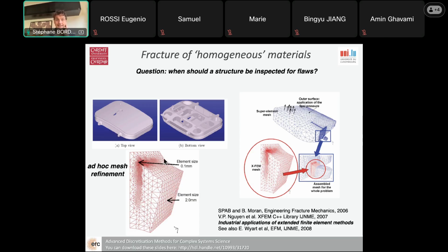That is, in fact, what everybody was doing before we did this work. People were computing the growth using extremely simple solutions, which were not even using finite elements. They were using some very simplified methods using codes developed at NASA called NASGRO and AFGROW. These codes look at the propagation of a crack in a plane, assuming the worst possible tensile load and assuming there is nothing around. So there is no other structure.